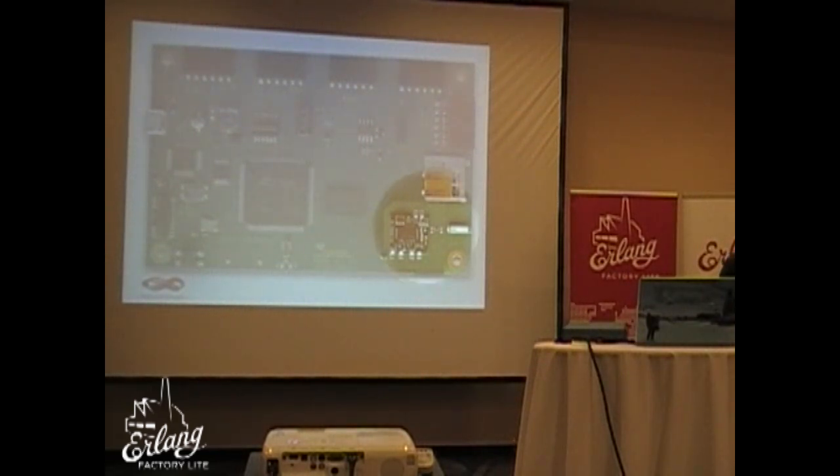It has an SD card slot, and this is, of course, where you boot your system from and plug in your application. The memory on board is only 300K on the CPU, so we also put SDRAM on top, 64 megabytes, because the CPU supports this. And this is plenty of space for an Erlang application. These boxes I showed you earlier with the conveyor belt, they also have this same amount of RAM, and there we never really came close to the limit at all. So there's plenty of space.